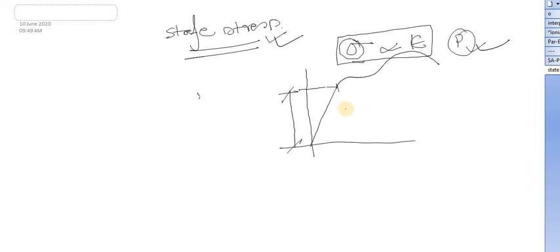Why? Because this is the elastic limit where stress is proportional to your strain, or we can say if we remove the load, okay, our material regains its shape. There is no permanent deformation. But if you exceed this limit, let's say here, in that case it behaves like a partly elastic material, and in that case there always remains a permanent deflection within your member. It is not at all desirable. That's why we need to find out this limit, or the limit of proportionality.